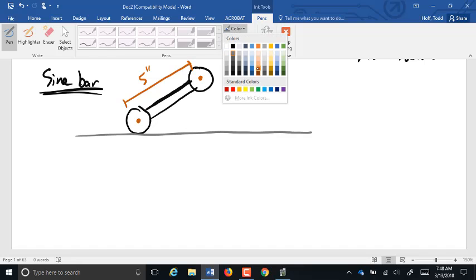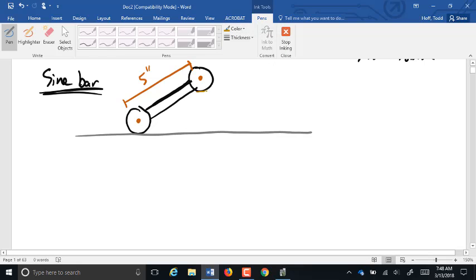And what we can do is build up a height here. Notice those round parts are fatter than the flat surface. And that is so we can tilt it and still set it on the round part. We can build up a required dimension here that'll create this desired angle here.